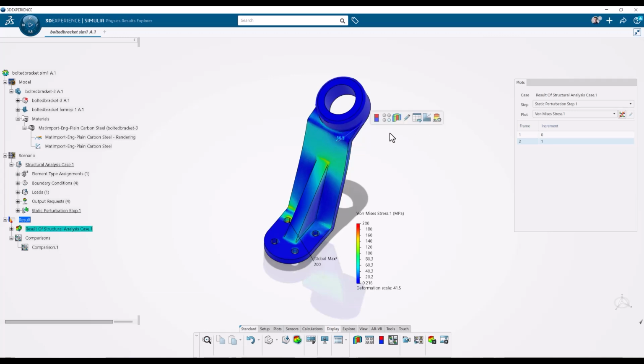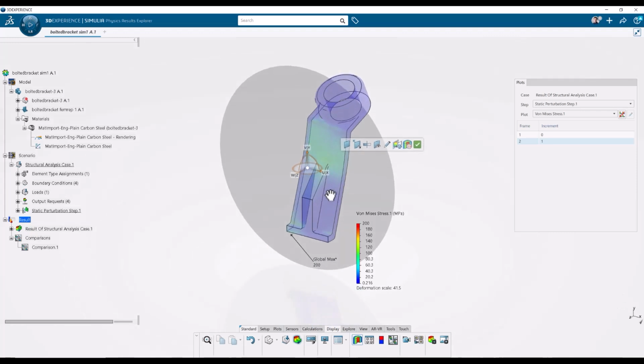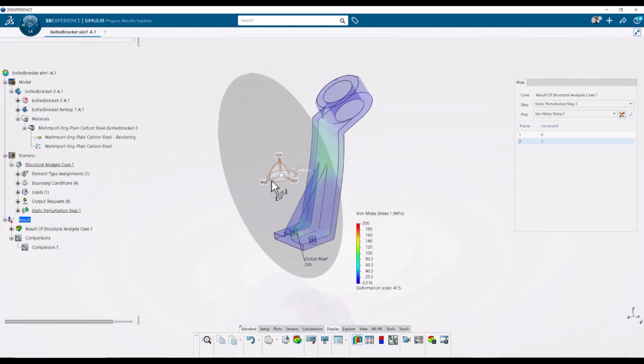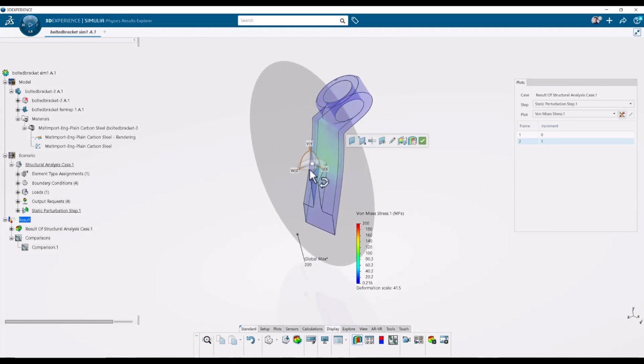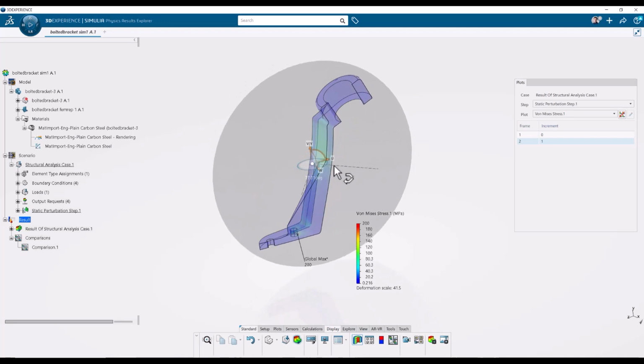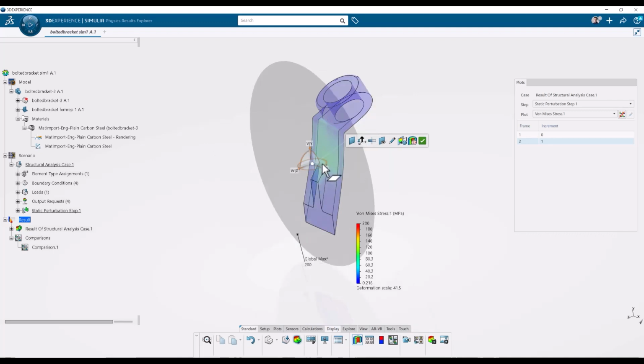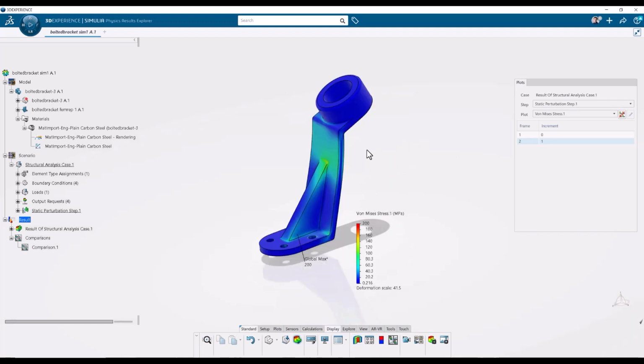If I go to the next button, there is the plot sectioning, so we can look inside the model, slide through it, see from a different view, make a cut like this. We can modify the cut in various ways. Maybe we cut in the Z direction instead, and we can deactivate it like so. We can export the field data, and we can do various plots and settings with this.